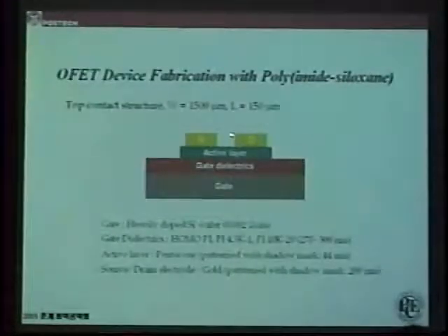This is the design of my OFET device. The gate was a heavily doped silicon wafer. The dielectric layer was polyimide with 3 different kinds, pentacene as the active layer, and source and drain as gold.